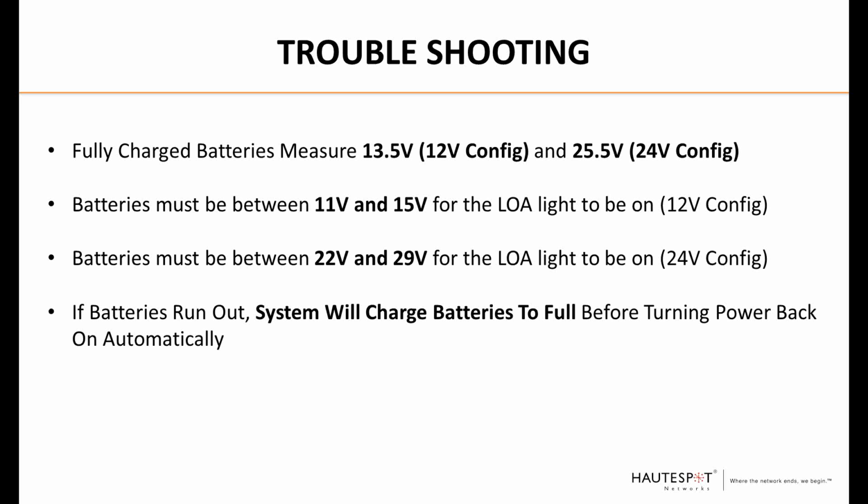And to reiterate, if the batteries do run out, the system will charge the batteries to full before turning the power back on automatically. That helps to prevent a scenario where you're only getting enough energy to turn all the products on, and then they turn off, and they can potentially surge and damage the devices. So it's a good thing to have a system that, once drained out, shuts down and only turns back on when the batteries are fully charged.